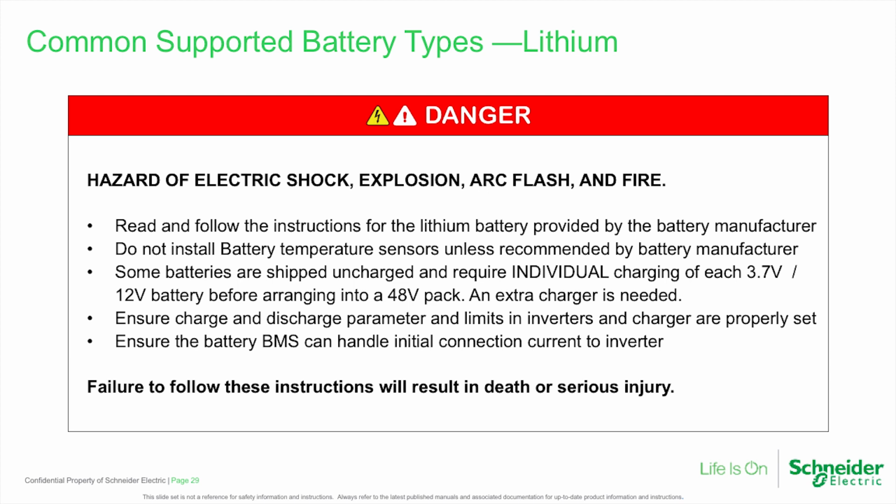Some of these lithium batteries come in 12 volt or even maybe 3.7 volt packs, and you have to individually charge these really carefully before arranging them into a 48 volt pack. So an extra charger is needed for that. You got to talk to your battery guy for that.